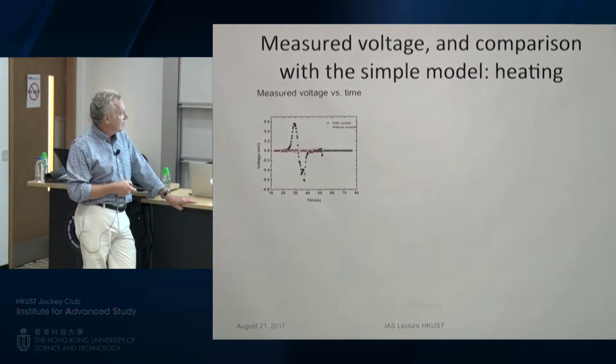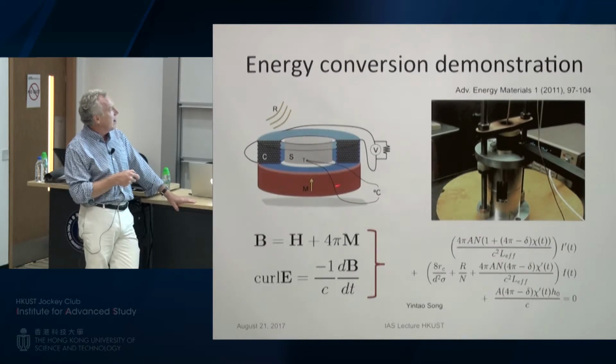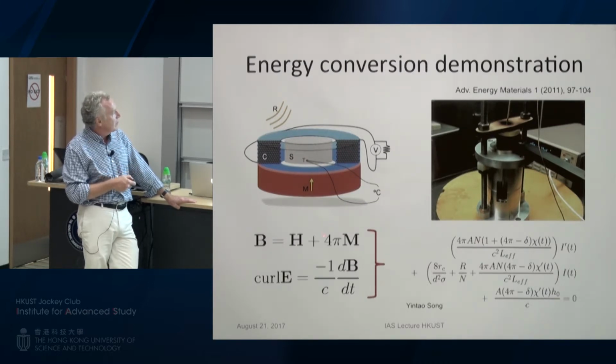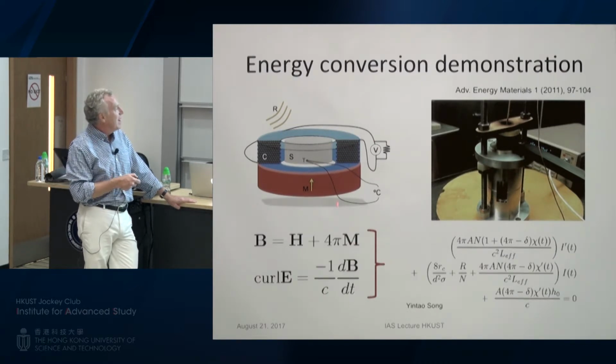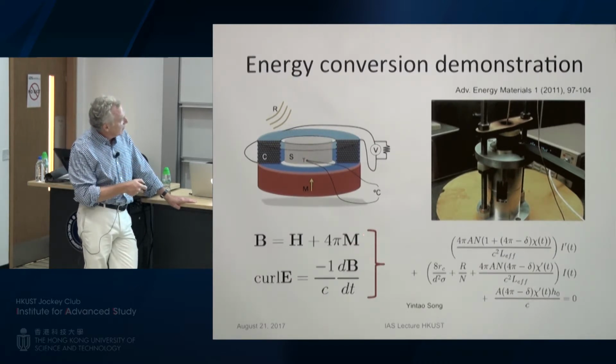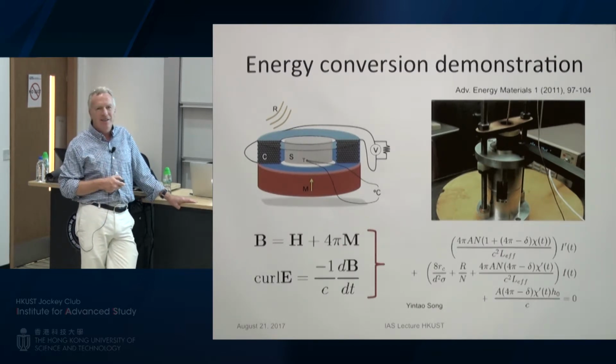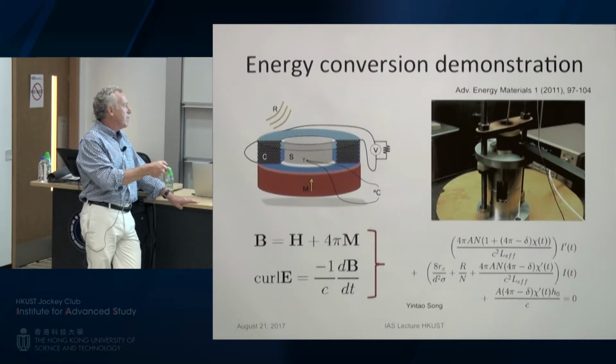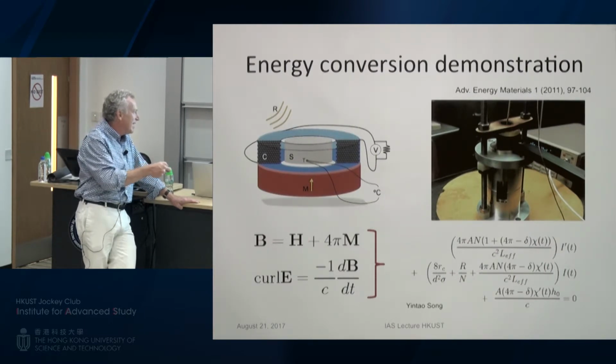Okay, go back to this. So you bias it, and now you heat it up just a few degrees through the phase transformation, especially if it has low hysteresis. And these are the two Maxwell's equations you should think about. When you heat it up, it goes through the phase transformation, and it gets a big dM/dt. So by this dipolar relation, dM/dt is partitioned between dB/dt and dH/dt.